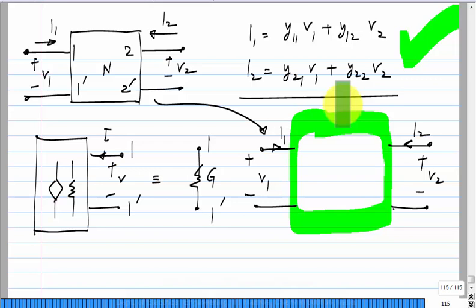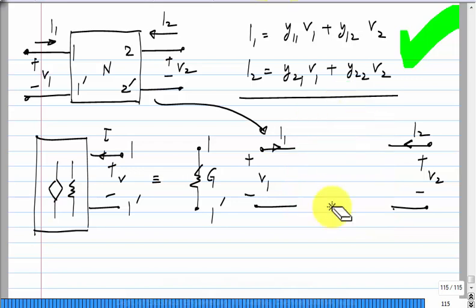Resistance and a? Where should be the resistance? Yeah. So, there should be a conductance Y11 across 1 prime, right? So, what will be the current flowing through this? Y11 times V1. So, that will contribute this portion of I1. Okay. What else?